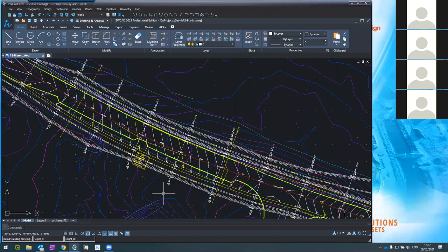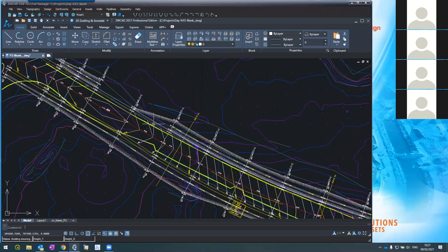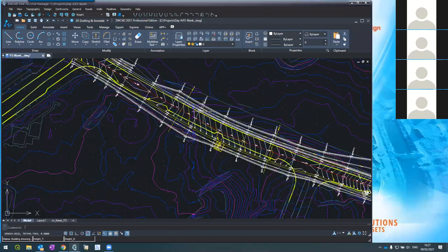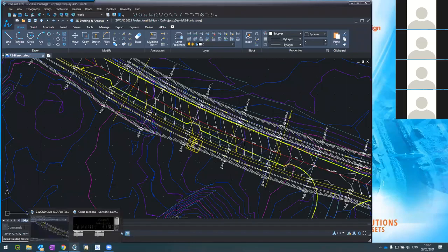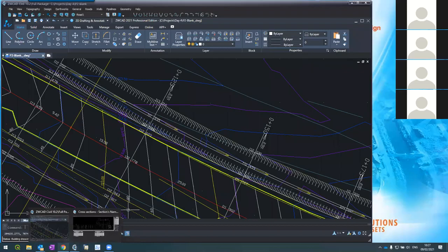see what happened. From here, 20 meters before, the super elevation starts. You can see it here on the right lane. And it ends 20 meters after, at that point. Here at that point, we have one side slope, and then 20 meters after, it goes back to 2.5%. So actually, if I go to see, for example, this section, 125,